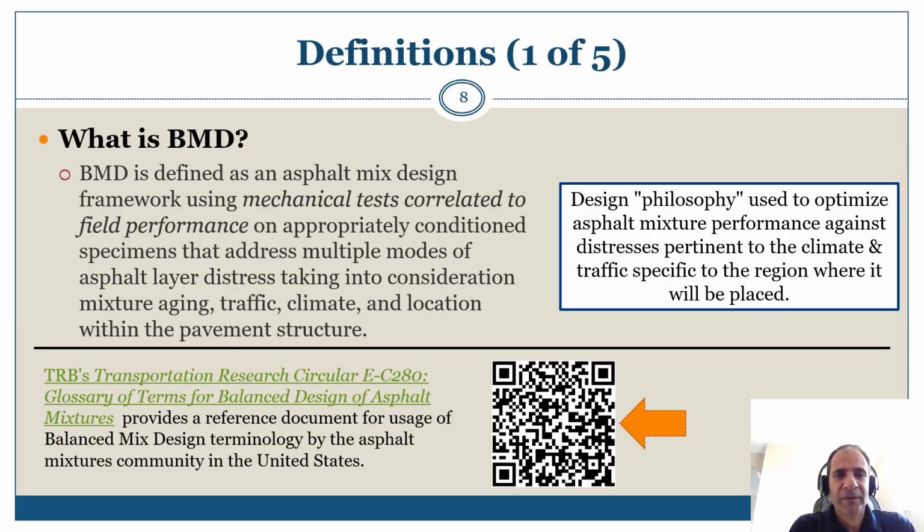Starting first with the definition of what is a BMD. According to the AASHTO PP 105 and to the glossary of terms for balanced design of asphalt mixtures, a BMD is an asphalt mix design framework using mechanical tests correlated to field performance on appropriately conditioned specimens that address multiple modes of asphalt layer distress while taking into consideration the asphalt mixture aging, the traffic, the climate, and the location within the pavement structure.